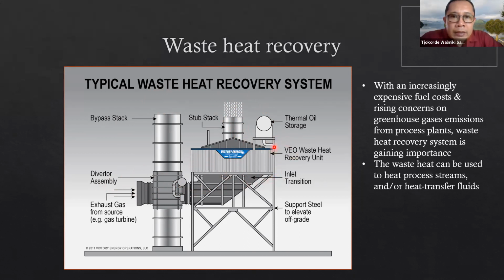Okay, and there are several technologies that are available to extract heat from the stack gas. You can use some heat transfer media, for example, thermal oil. This is a heating media. You can contact the gas with process fluid in a heat exchanger, for example. Anything that works. Okay. And this is the stack that has been cooled down because of this heat transfer.